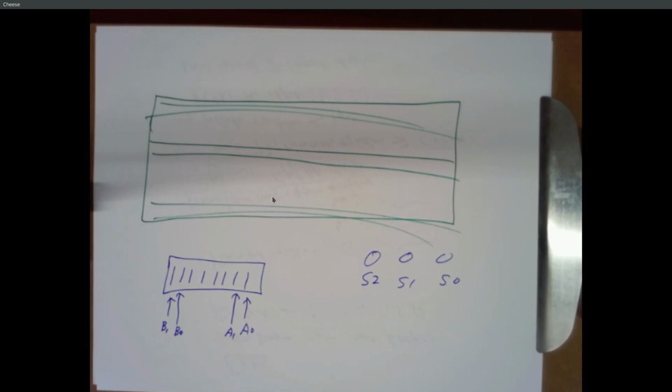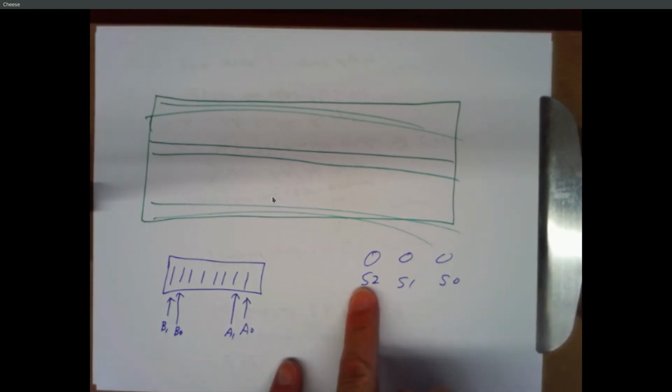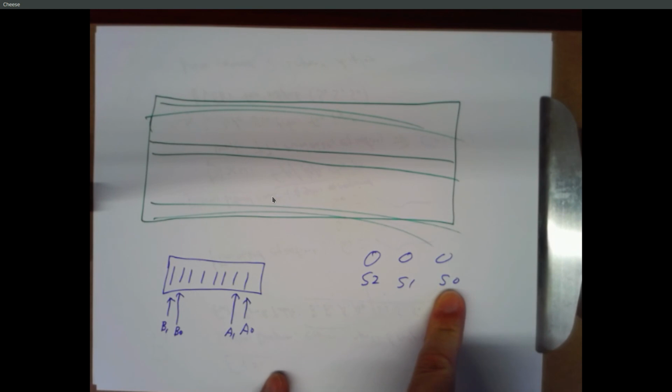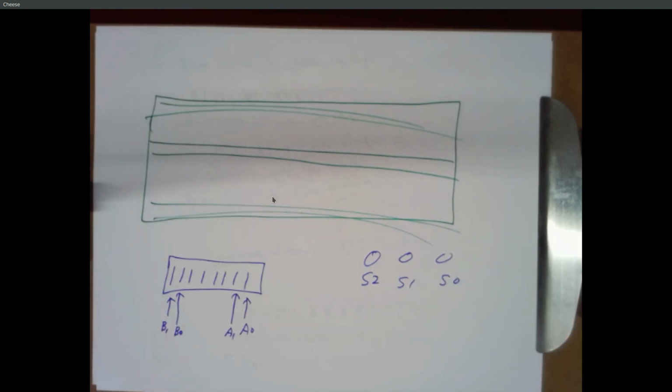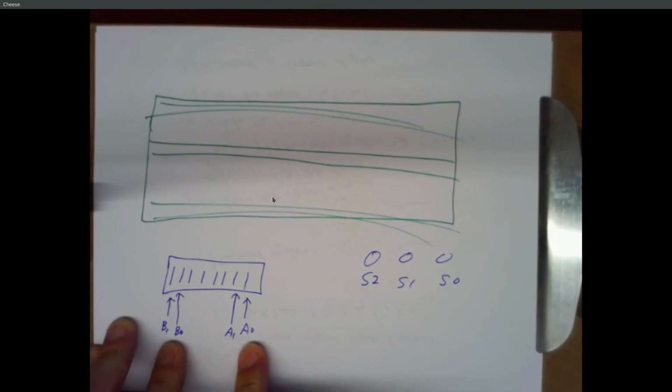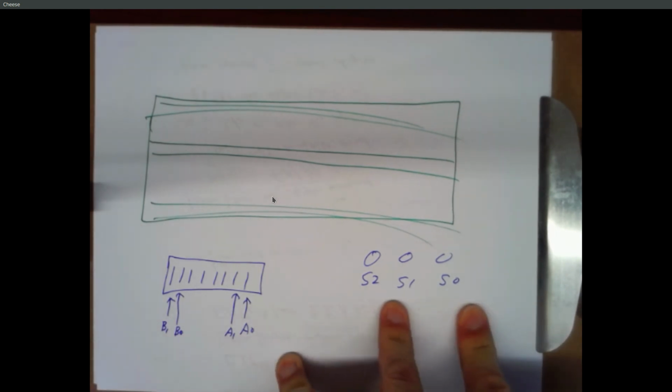And it sounds like a trivial OCD kind of thing, but I have watched so many students trying to debug a circuit that's either already working or is failing in some different way because the way that their wires ended up running, they had S1 and then S2 and then S0. And now they're trying to add 2 and 3, and they're hoping to get a 5. And so a 5 should be, well, that should go there, and that should be a 1, and that should be, right? And there's so many opportunities to get confused, and it's already a complex enough lab as is. Make life easier on yourself, right? Keep your switches in a well-defined order, keep your LEDs in a well-defined order, so that you're not chasing ghosts.